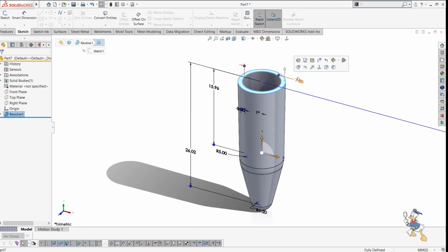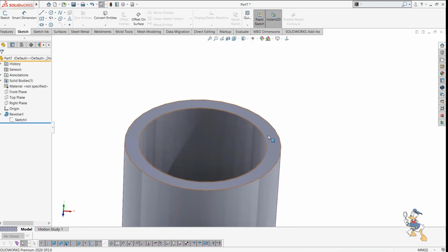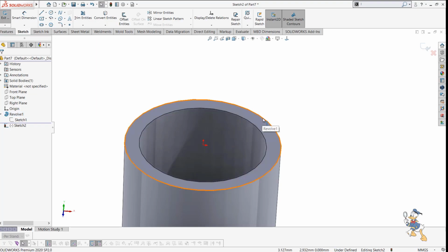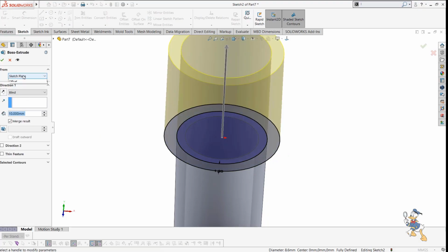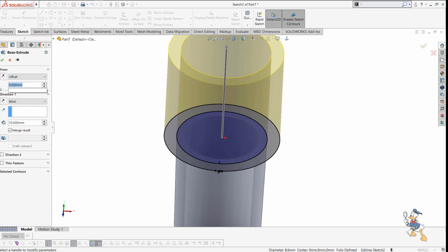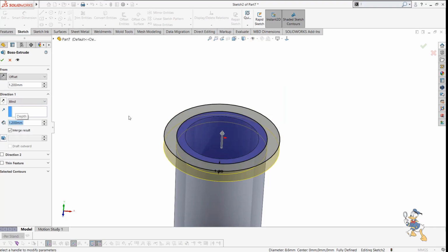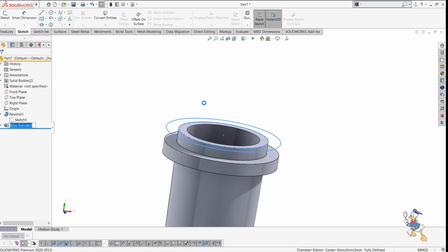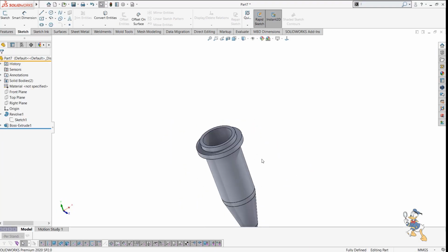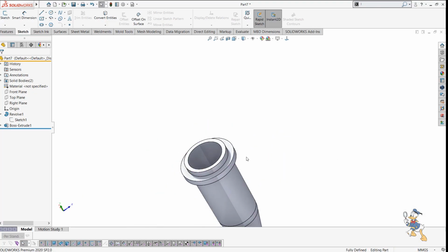After revolving this one, I can generate a plastic component easily. So after generating this plastic component, I can generate some sketch, and I can offset the value up to about 2 mm or 1.2 mm, and then I can extrude it up to a 1.2 mm offset value. This is how we can generate a plastic cap over here. So this is a tube of 1.5 ml.